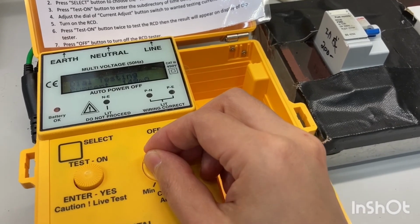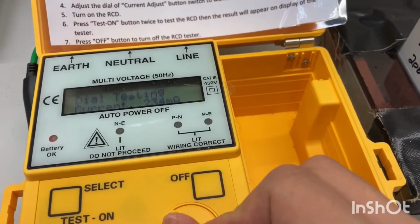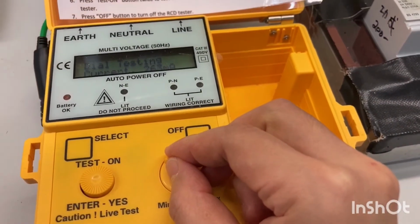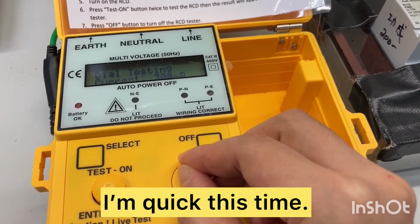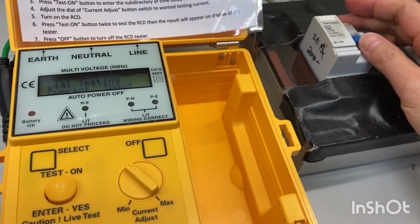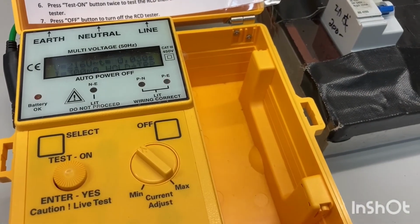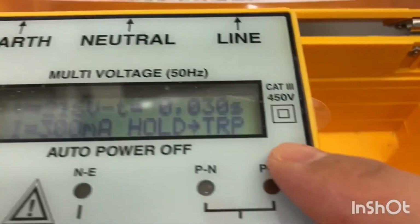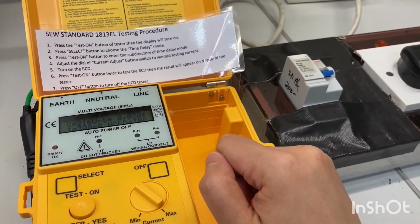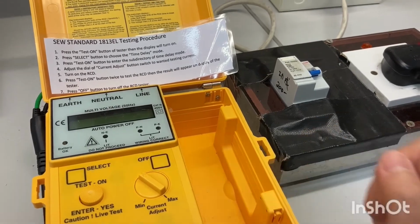The last testing current value is 300 milliamp. And the same procedures are repeated. For a residual current value of 300 milliamp, the tripping time is 0.03 seconds. And this is the last set of data.